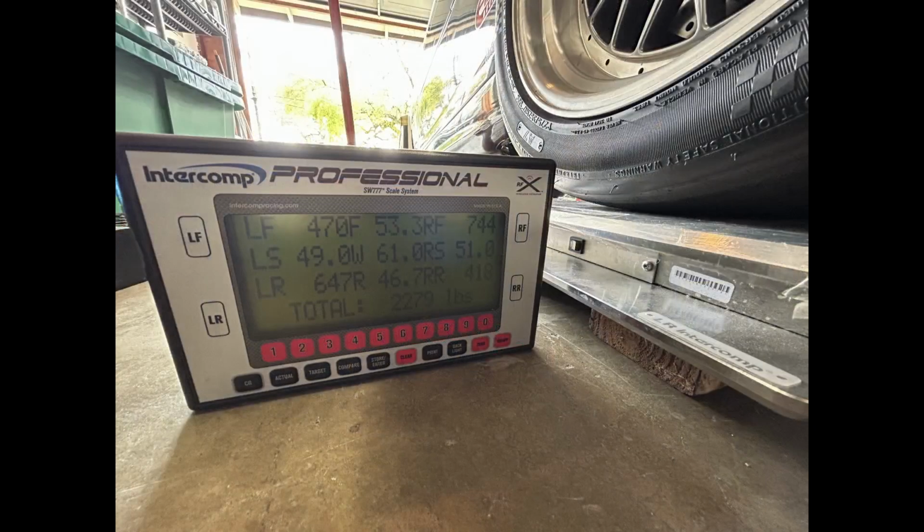Let's also consider that these data are static. So we're isolating the kinematics, compliance, and spring rates of the chassis and the tires. Effects from inertias, damper rates, and hysteresis are not relevant in this experiment. That said, for fully dynamic correlation results, you can look at the first devlog entry. It's far from perfect, but it is getting better, and I hope to talk more about that soon.